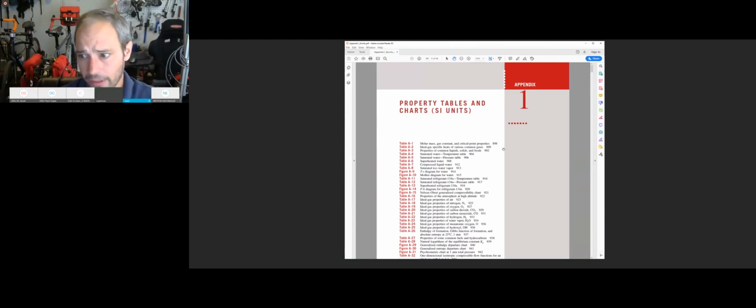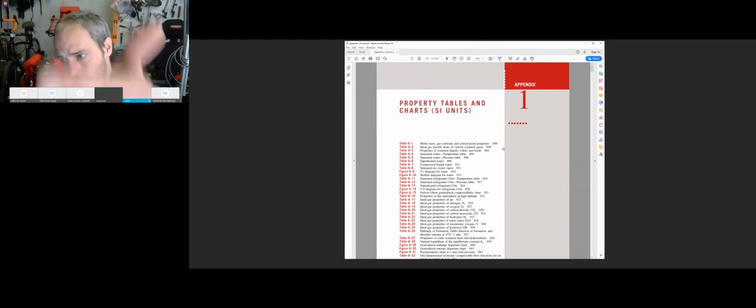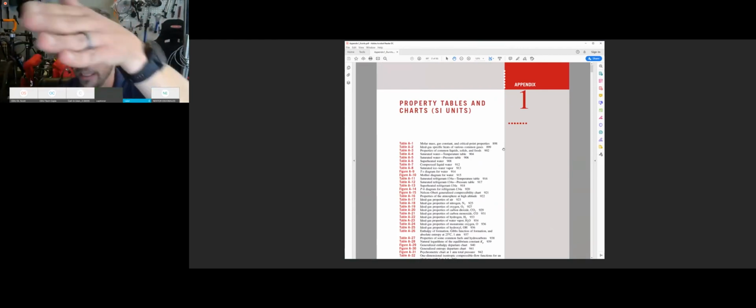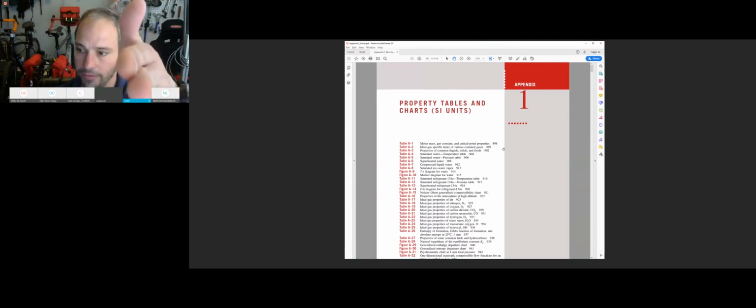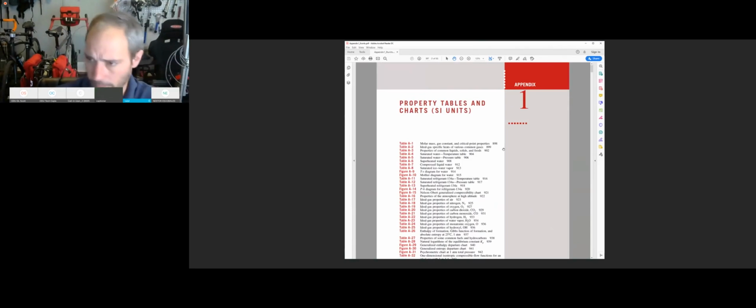But what the steam tables give us is the energy, the density, the internal energy, the enthalpy, and the entropy. You learn all that in thermodynamics. It gives you the values of those for the case where the water is just about to begin to boil. From the pressures, from the minimum pressure is its triple point, and the max pressure its critical point.